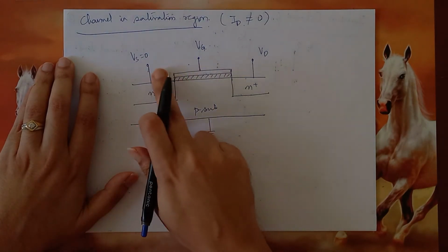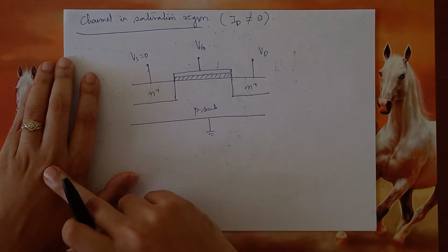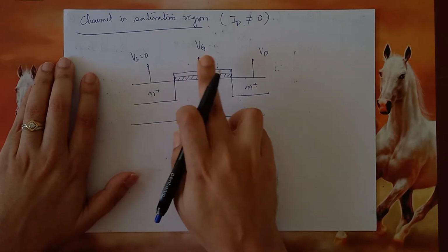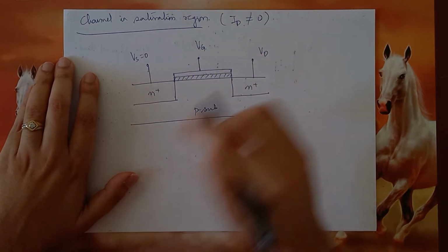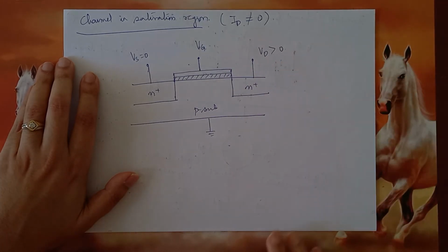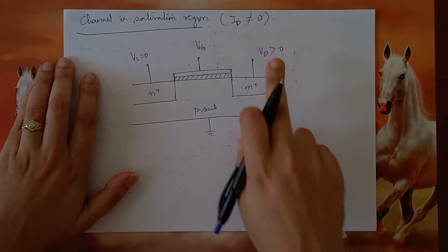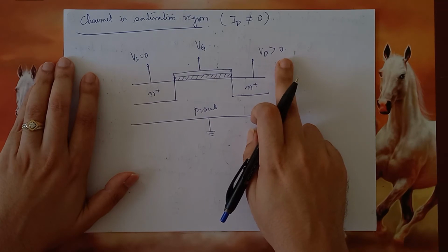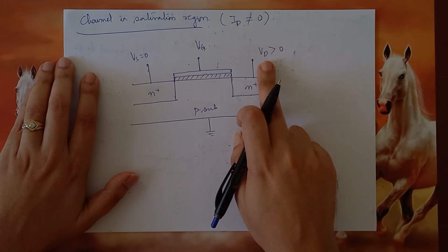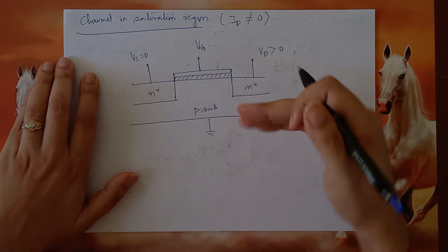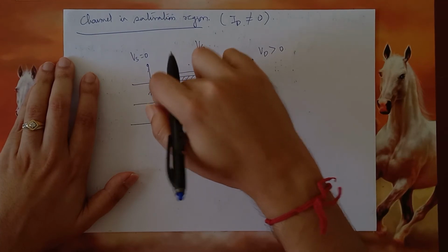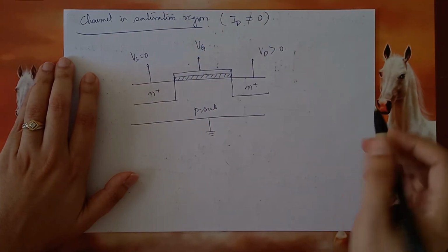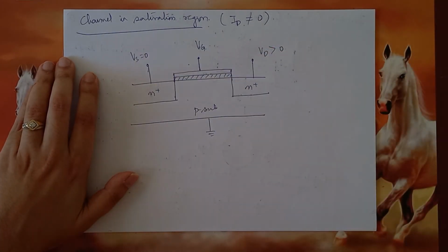So therefore, because the gate to source voltage is now quite large and the gate to drain voltage is smaller, what will happen immediately we can say is that because the drain voltage is now non-zero, the channel will carry electrons from the source to the drain. Thereby, the drain current will flow from the drain to the source.